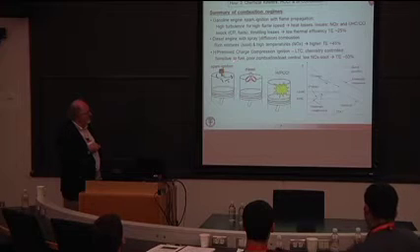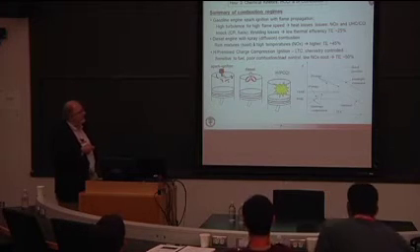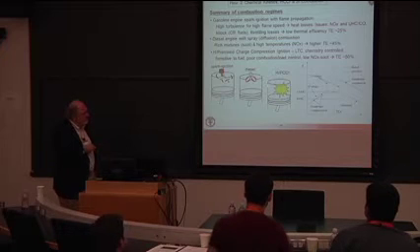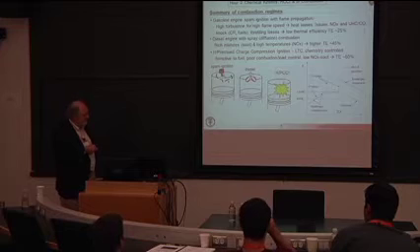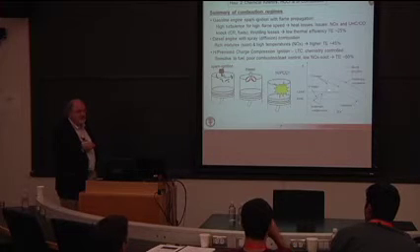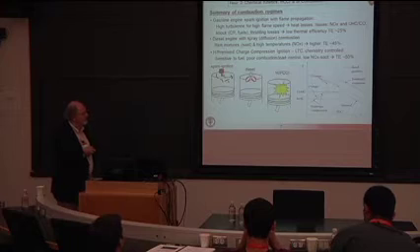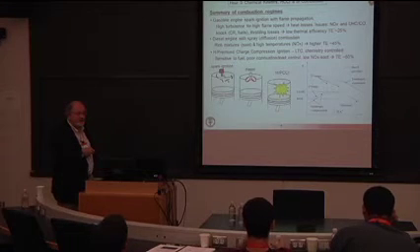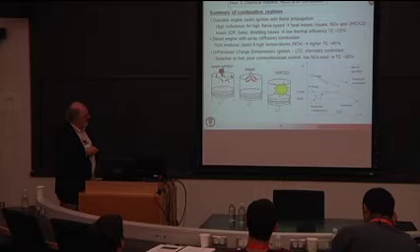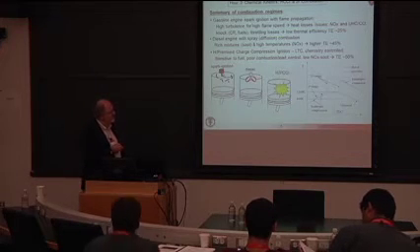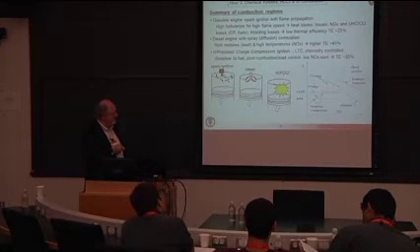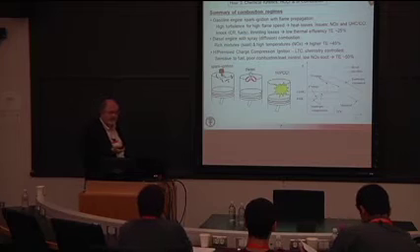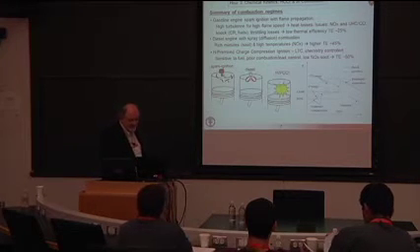The other thing is that we have poor load control, because if all of this fuel goes off at the same time, there's no way of delaying the combustion. I get pretty much a vertical line over here, which leads to very high in-cylinder pressures. That means I can only operate at light loads. One advantage, though, is because I have a very well-mixed combustion situation and I'm operating at low loads, I get low temperatures, which means low nitric oxide, and there's no rich regions, so I don't get soot. That's the big appeal of HCCI.